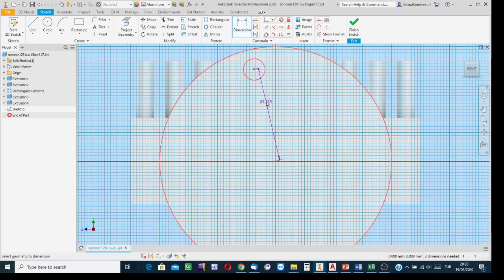If you move the cursor not many units but only a few units and then click the mouse, you see Inventor understood that the distance to input is the radial distance, the shortest distance. After that, make one more click to be able to input the value. Say that the radial coordinate for the center of this with respect to the common center, which is the center of the surface, a circular surface, let's say in this example is 70.